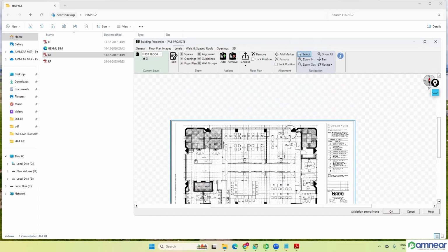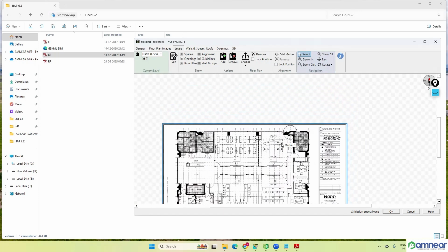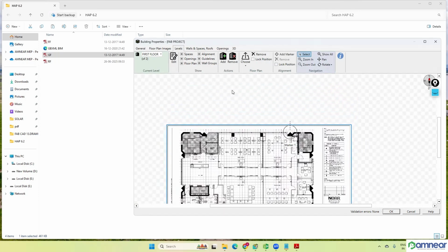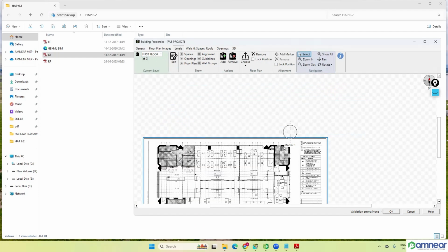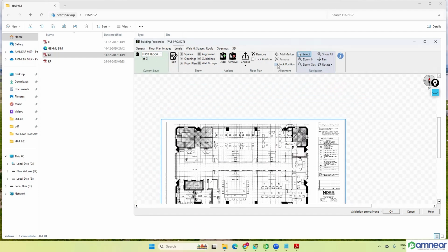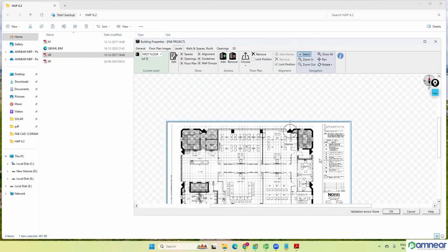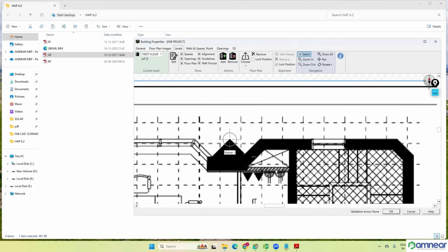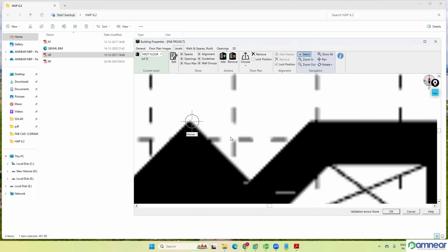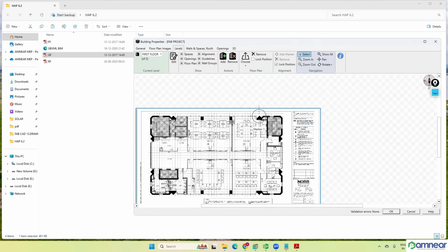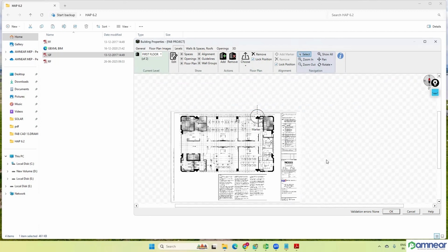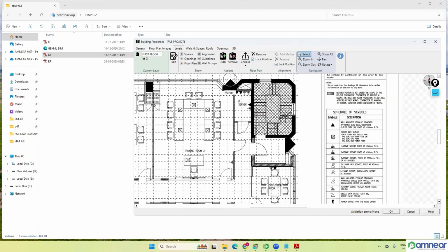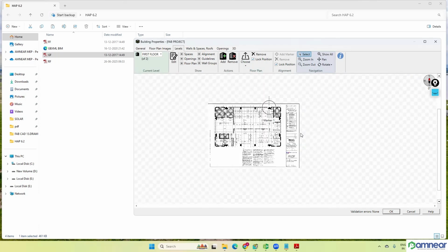Okay. Now what you have to do, the marker you should not move, the drawing you should move. Because if you are moving the marker from the ground level itself, the marker will move. So once you have fixed your marker in the bottom level, you should not move the marker, rather you can move your drawing. So the marker should always be in locked position once you have set. Drawings you have to move, then on the same point you have to keep it. Otherwise the 3D will not generate perfectly. Okay. Now lock position. Now ground floor and first floor have the same point, origin.